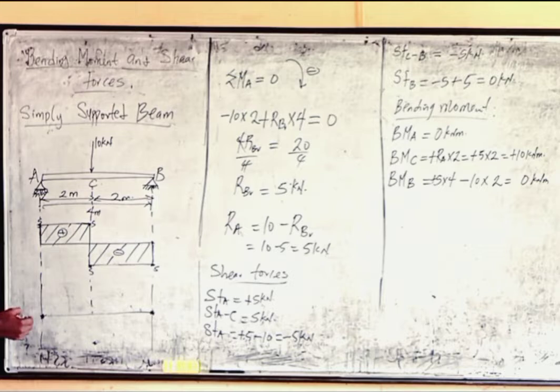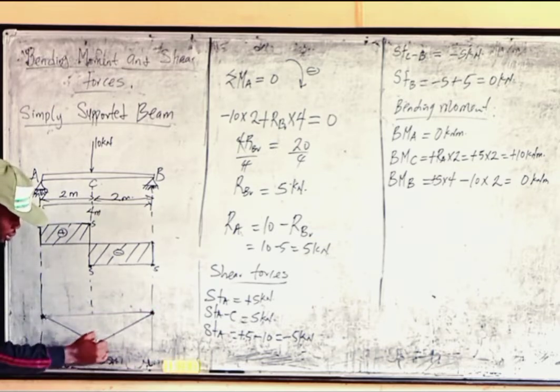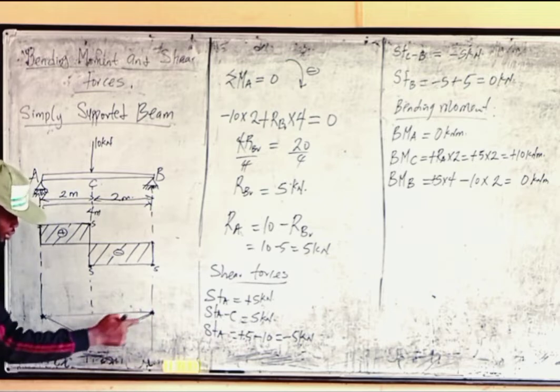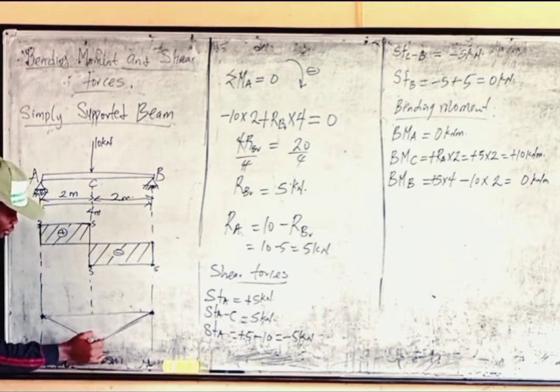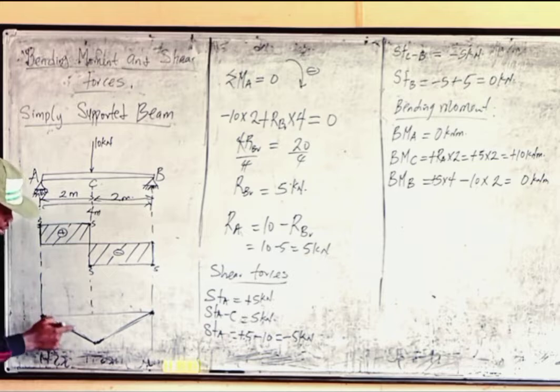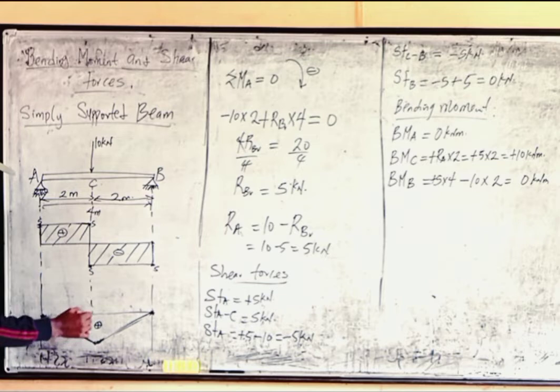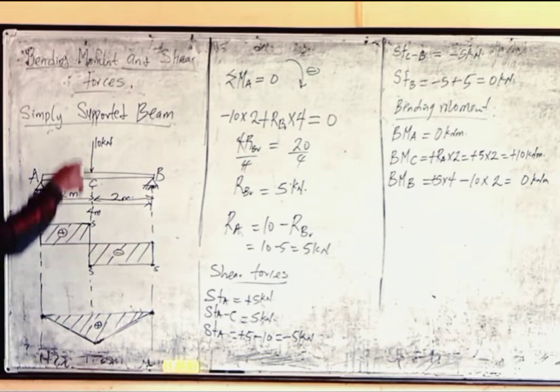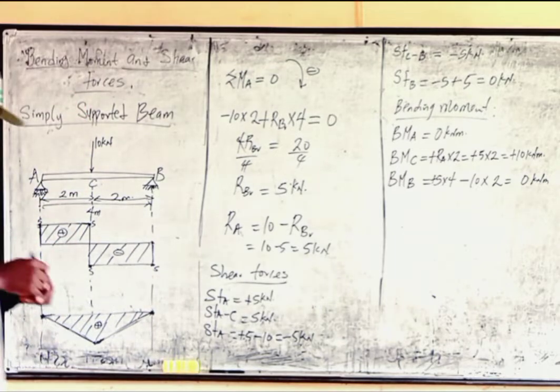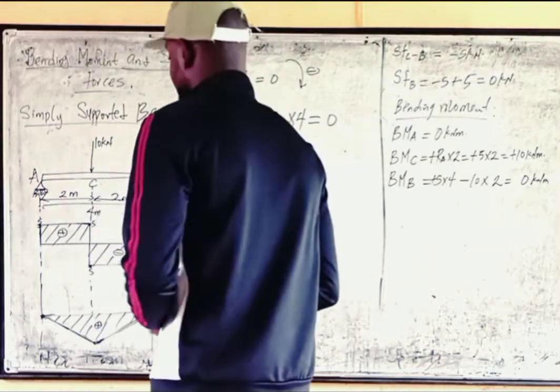So the next thing, we just draw a diagonal. Remember, from the point we join a diagonal, it's still straight. So just join a diagonal, and then this one with a diagonal. This will give us the bending moment diagram for this problem. Remember, this is positive. This is how the bending moment diagram looks. The beam tends to bend downwards. This is what we're having for this problem.